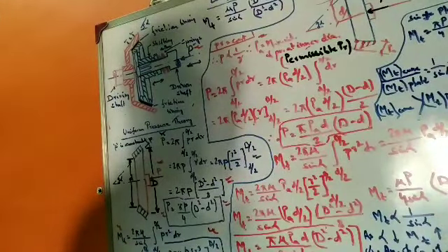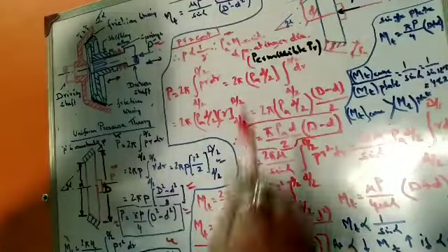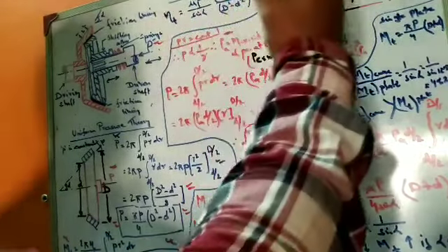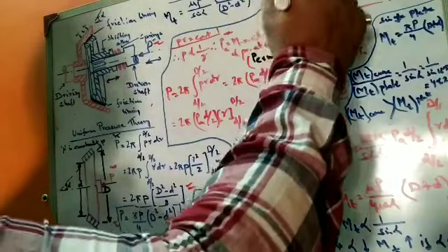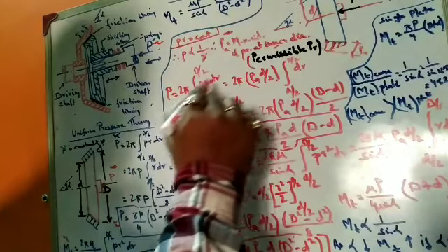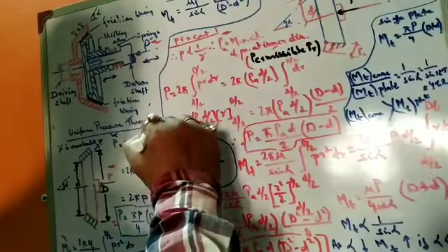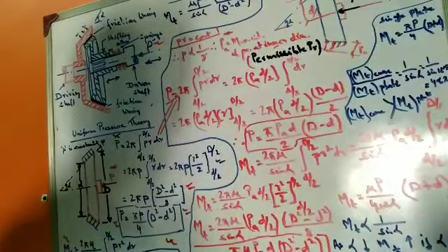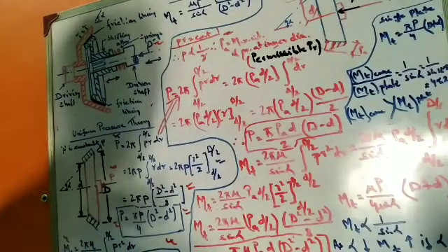Now we should base our mathematical model and calculations on this maximum pressure. That is the basic concept of the design: we should always deal with the maximum pressure. Now, this expression 2 pi r dr is the one we should be operating with. First we operated it for the uniform pressure theory. Now we should operate it for the uniform wear theory, where you could see 2 pi r p r dr.